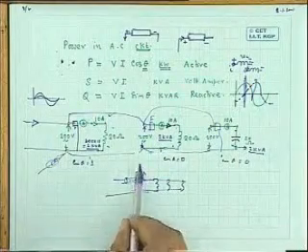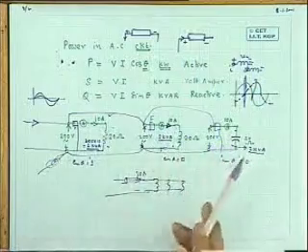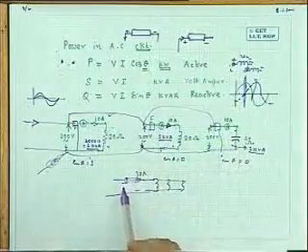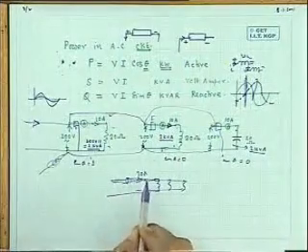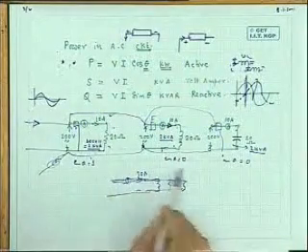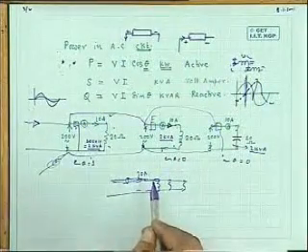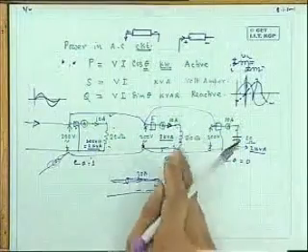So the supply authority has to invest a lot at the initial stage, with the understanding that all of them will carry some 10 ampere current. So the conductor cross section matters, and also, as you know, these conductors have some resistance, so in the transmission lines there will be power losses.